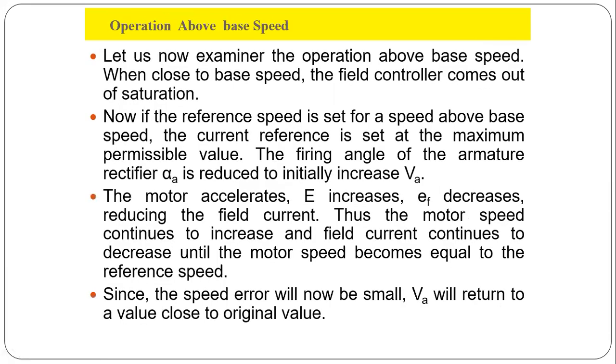Now let us understand the speed control operation above base speed. Before that, we studied the operation below base speed. Let us now examine the operation above base speed. When close to base speed, the field controller comes out of saturation.